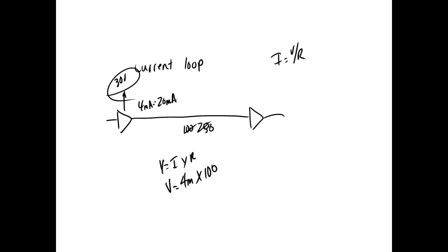You can put it across any resistance, until it raises the voltage as high as it can, then it says overload, right? You understand? And then it'll shift over to a different range. It shifts another resistive circuit in there, right? And that's the way your digital meter works.